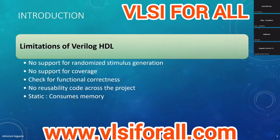It's random, so there is a high chance that if you think of this as a state space, you can cover all the corners of the space. This was not possible until we had SystemVerilog. After SystemVerilog, we got support for randomized stimulus generation. We'll see in more detail going forward how we use randomized stimulus generation using constraints and randomization.